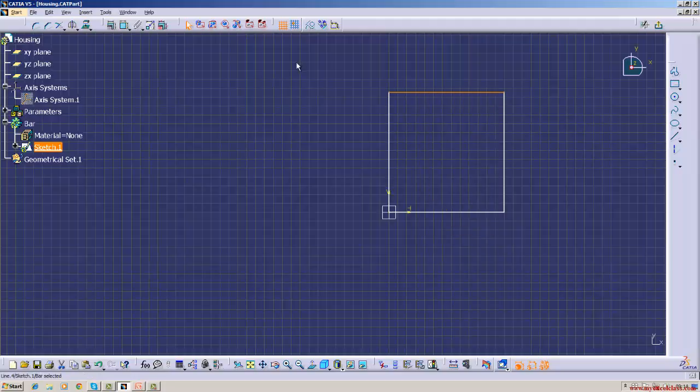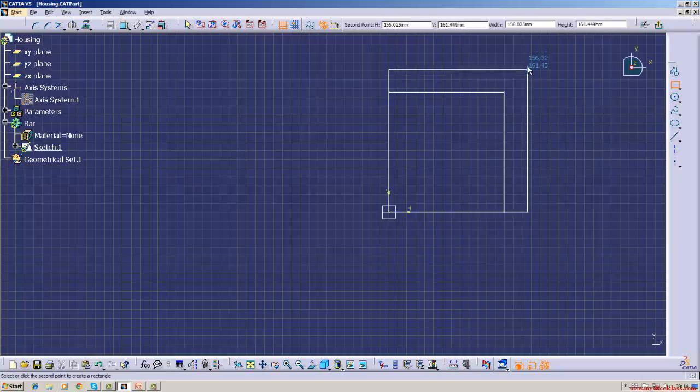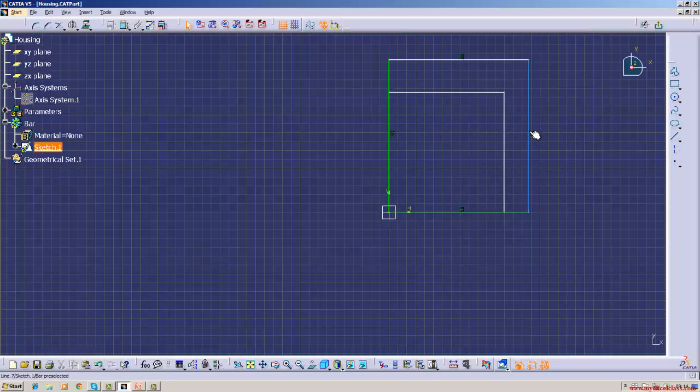Suppose I want, see, because I have not selected this. Suppose I select and then draw. Select and then draw once again. Now I will draw it. See, constraint I will apply. This should remain vertical always. This is also vertical. This is also vertical. Okay. This is how, in order to apply constraint, this should be selected.